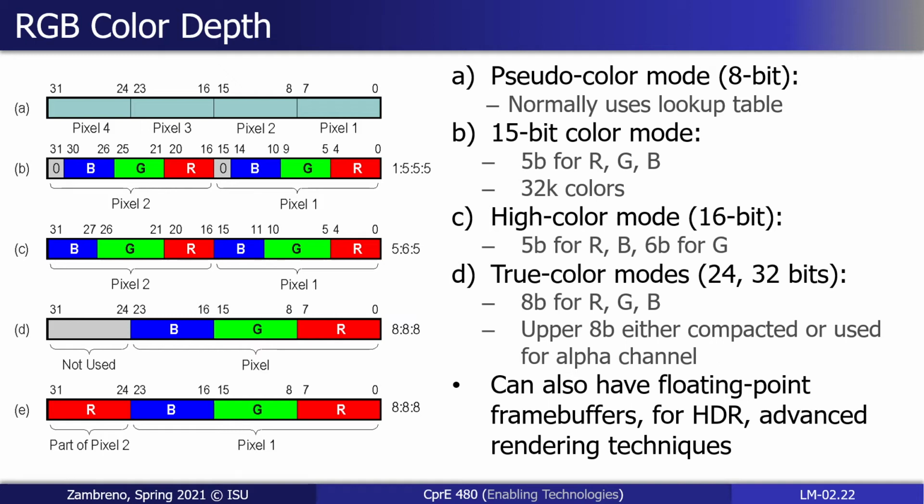So you'll see things like 8-bit color, or 8-bit storage per pixel, which isn't a lot of information, right? That's 8 bits to store all of the red, all of the green, and all of the blue. So typically, if you see something that has just 8 bits per pixel, there's some other piece of hardware in the loop that is doing something with that information. Maybe it's applying the lookup table like we talked about on Tuesday. That 8-bit information actually isn't storing anything relating to red, green, and blue. It's storing an address into an intermediate buffer, a lookup table that actually maybe now has more bits per pixel associated with the red, green, and blue.